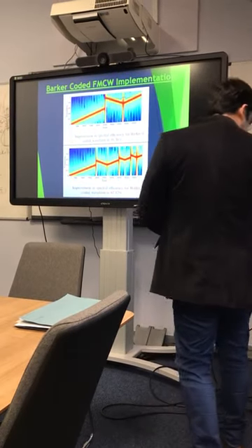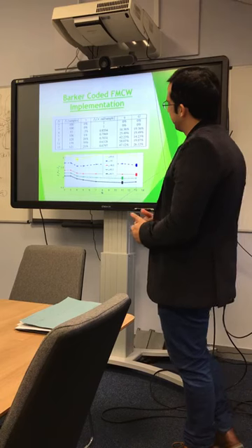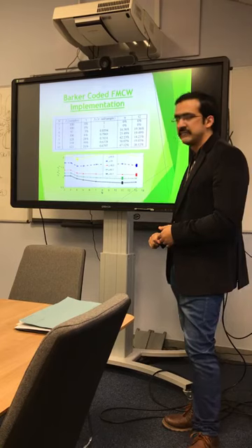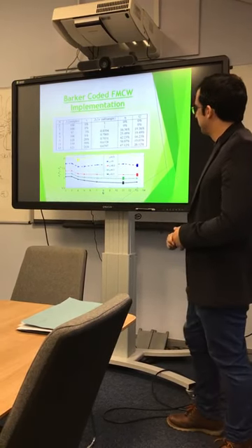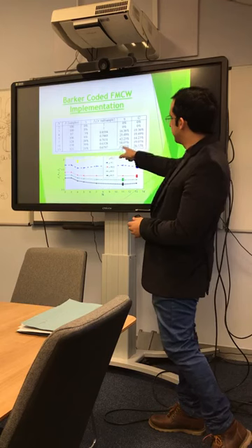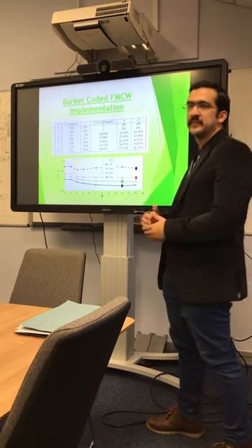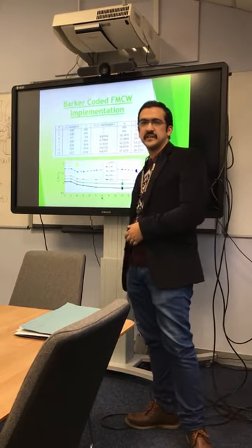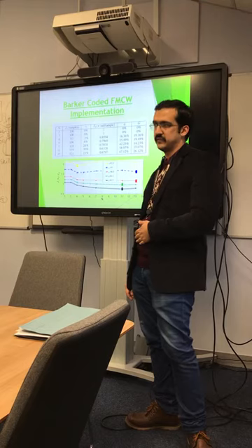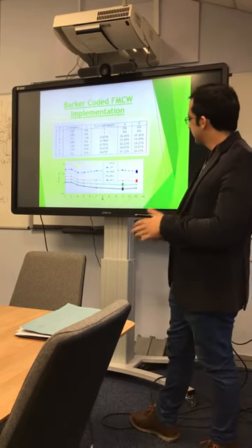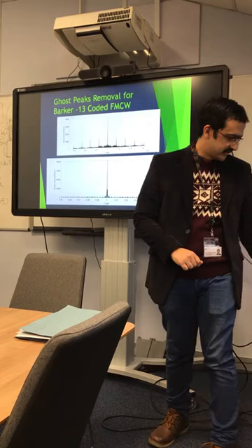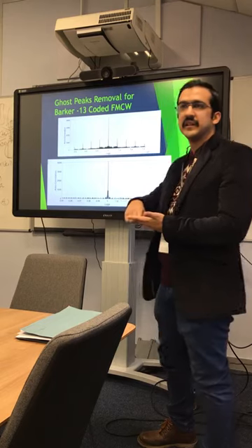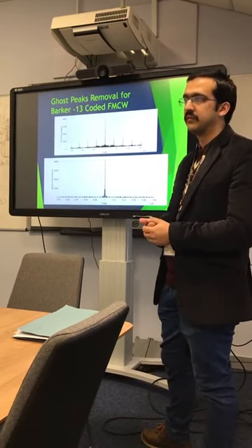So after that, we jointly optimized 2 parameters, which were the range resolution and the bandwidth efficiency or the spectral efficiency. For the barcode coded 11, you can see that there is a maximum spectral efficiency of 58%. So if you are willing to tolerate 39% loss in the range resolution, barcode coded 11 is the best waveform in our case. Nevertheless, the reason to show you all this, and one simulation I want to show you, is that the ghost targets also disappear because of the frequency shift that we introduce in our case.